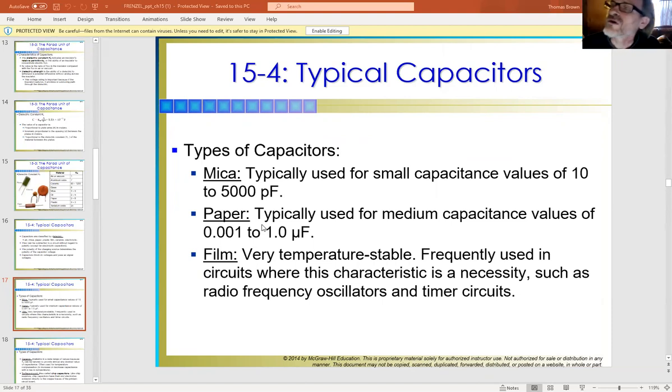If you look at the late 90s and early 2000s, a lot of electronics were experiencing premature end of life cycles for their products. What happened was they were using inferior paper, and so these capacitors were literally breaking down. The rest of the circuit was fine, but the capacitors were breaking down on these boards because the material they were using was junk. They weren't even lasting, because typically off the shelf, electronics should last 5 years.